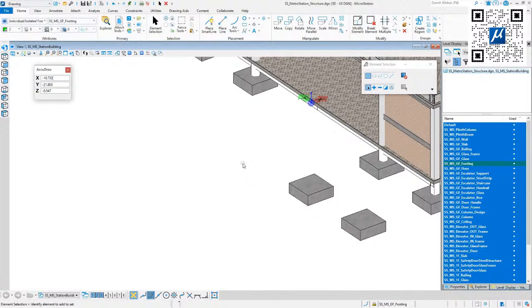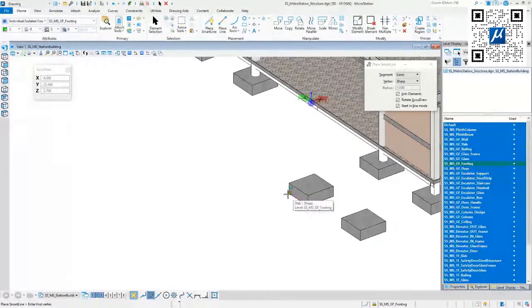And to be sure, where is the origin from AccuDraw? We simply start drawing. I take a smart line tool, for example, the polyline tool, and then I snap to an existing element using my AccuSnap. And the next thing I do is a left click to accept. And you can see that we get a little blue square at this position. And this is the AccuDraw origin.